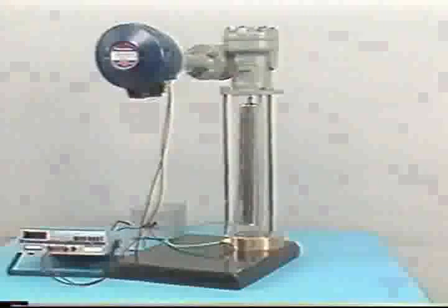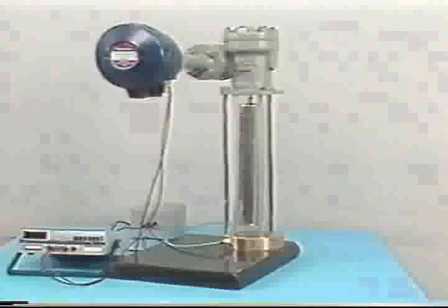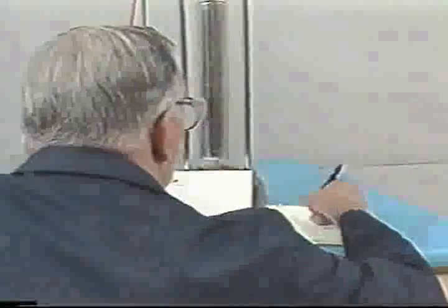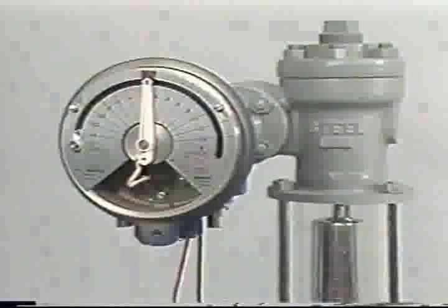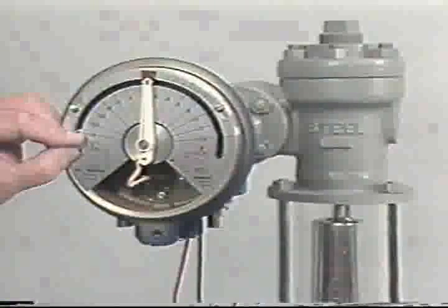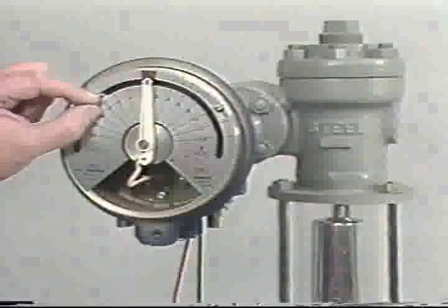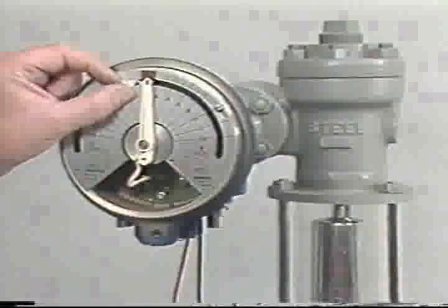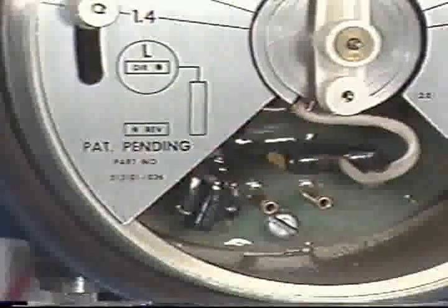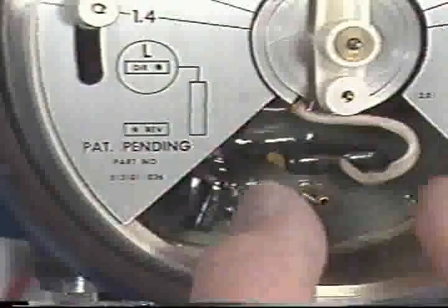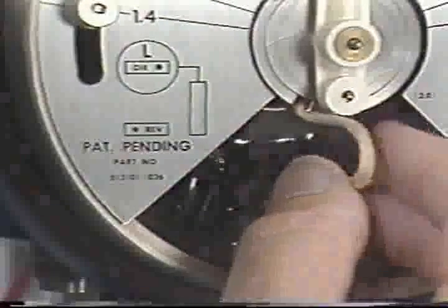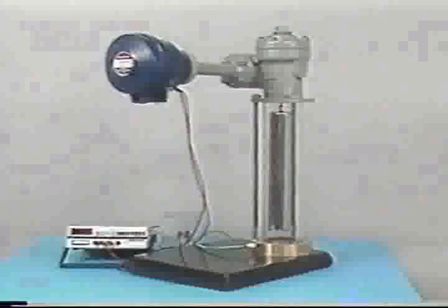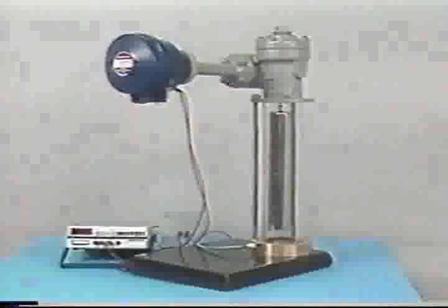Let's take a moment to review the steps we've just seen before we begin calibrating the instrument. To calibrate a displacement level transmitter, you first must determine the buoyancy value for the input liquid's specific gravity. Next, you'll determine the correction factor used to compensate for the manufacturing tolerances of the torque tube and the displacer weight. Set the pointer on the calibration plate to the value you determine. Then, according to the manufacturer's instructions, you'll set the plug for reverse or direct action and balance the amplifier to produce the correct input-output relationship. Now you're ready to begin calibrating the displacement level transmitter.